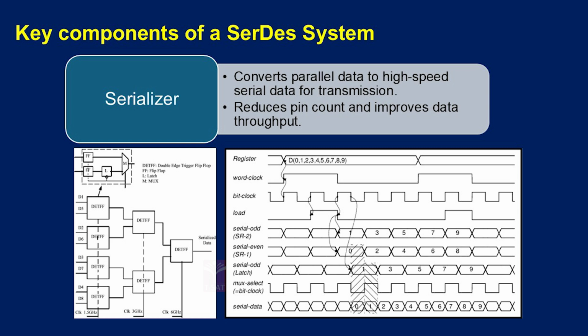Serializer, yes, is one component. In this component we have serialization, converting all this data into serial data, and there are different ways to do the serialization using even and odd kind of arrangement, and you definitely have a bit clock to do that, and this is your overall serial data. Now if you look at it, there is a kind of latency from the data here to the final data here. So that latency we need to make sure that we are calculating, and we are covering that latency when we are sending the data into the channel to the receiver.